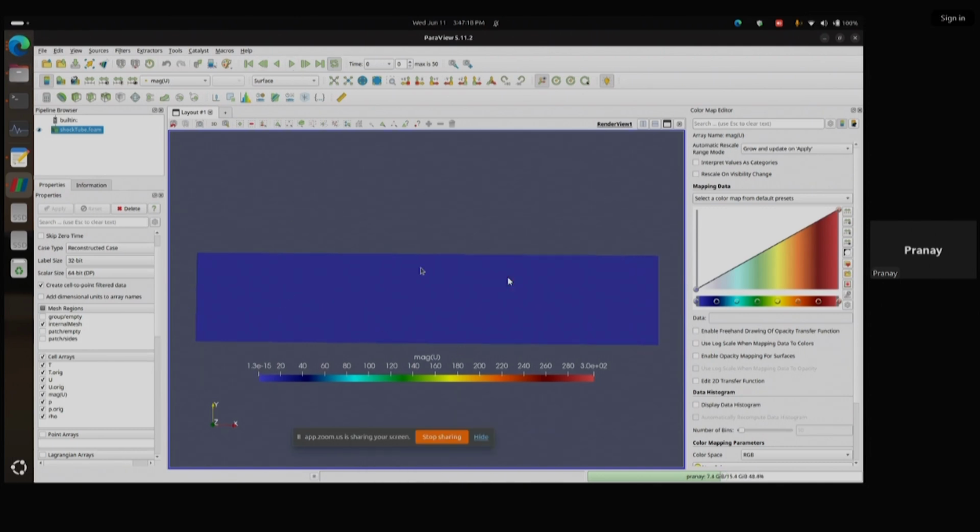So yeah, in the beginning it was zero. At time equal to zero, the velocity was zero. But as I click onto the next frame, that is at time equal to 5 into 10 raised to minus 4 seconds, that is 0.0005 seconds, I see an increase in velocity, a spike in velocity, a tremendous spike in fact. From zero, it rises up to 300. And that is what the shock waves create. The change in velocity, the change in pressure which we saw earlier, and we will see how temperature and density are changing. So I'll let it run till the end.